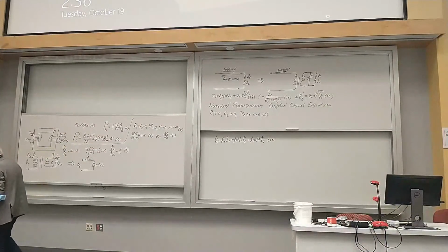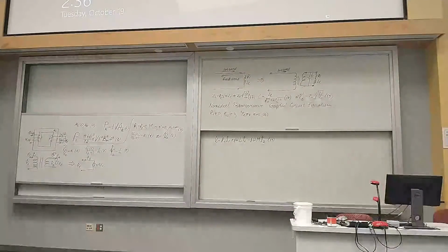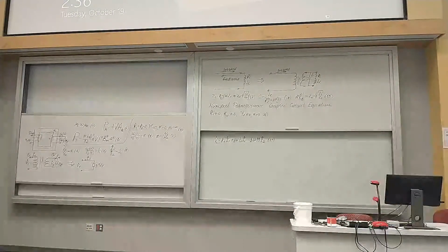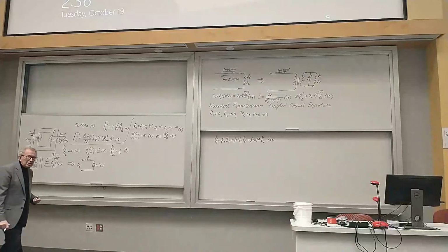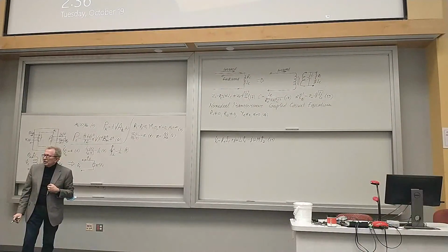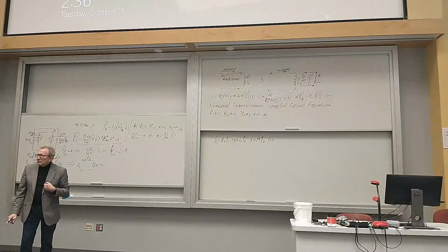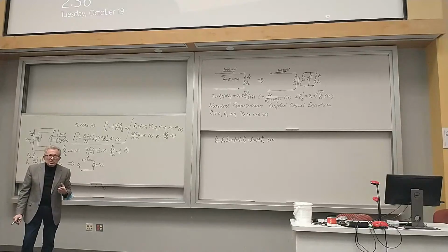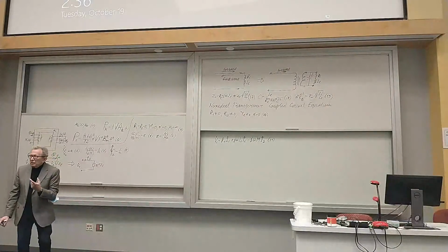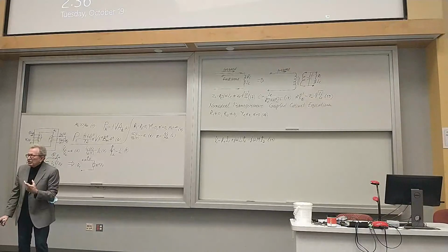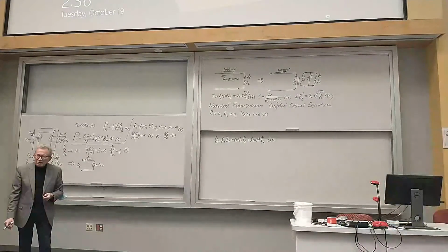In the case of transformers, this sign minus is placed here because we can use Lenz's law. You see that current in the secondary winding is induced by the magnetic flux created by the current in the primary winding. And this induction, according to Lenz's law, is always in such a way that it counteracts the cause of induction. What is the cause of induction? The current through the primary winding. But this current exists because the voltage is applied to the primary winding. So the cause of induction is a voltage applied to the primary winding. And that is why we put sign minus.